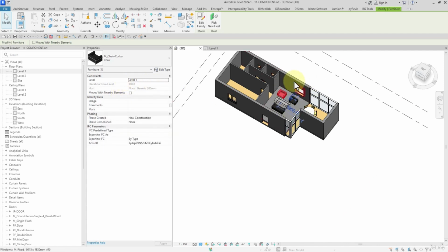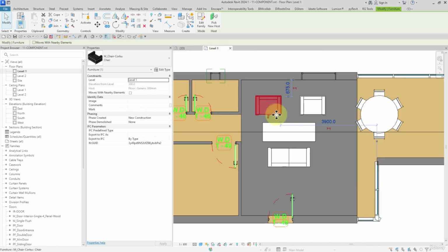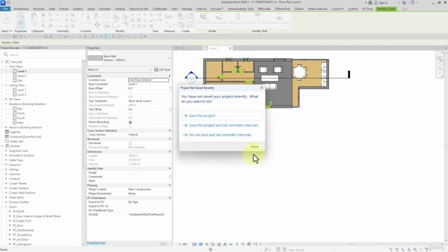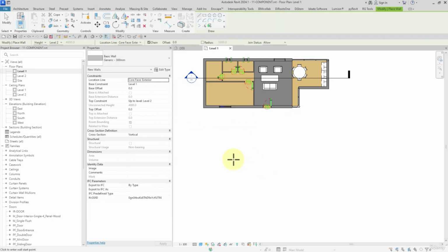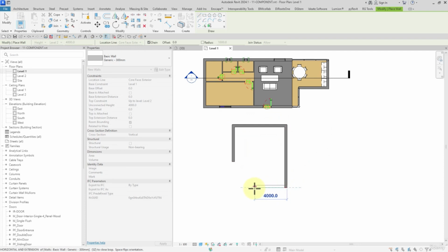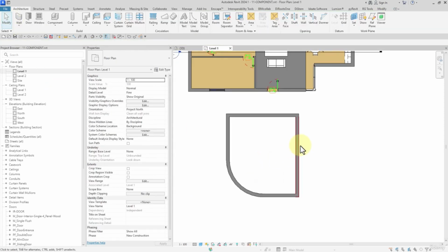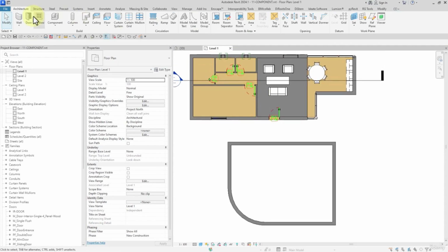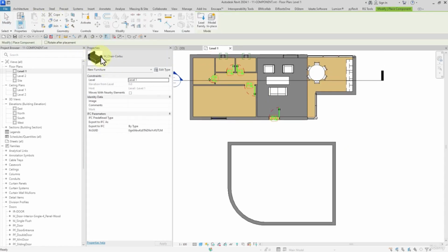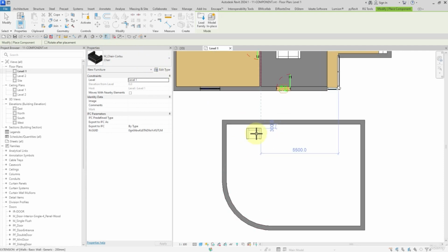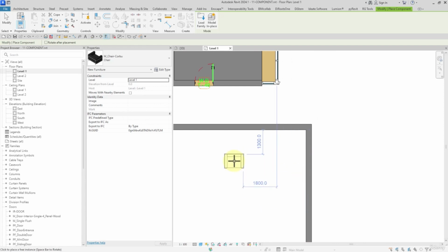If I associate an element to this chair, then if I move the associated element, the chair will be moved too. For instance, I select this wall and then I draw it this way. Watch this. Great. Then with an arc. Very well. Then here, if I select the component and then select the chair from the type selector, I can place this, just watch the temporary dimensions.